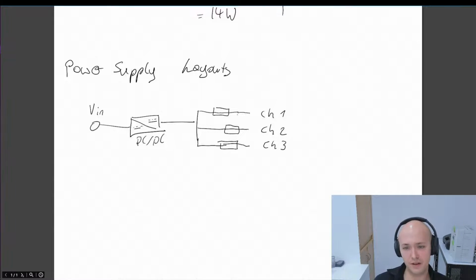That would be a very good fit for that application. But of course, we also have to look for all these fuses, and we would need to have very thick traces transporting the current through the board. So maybe that's not the optimal design.